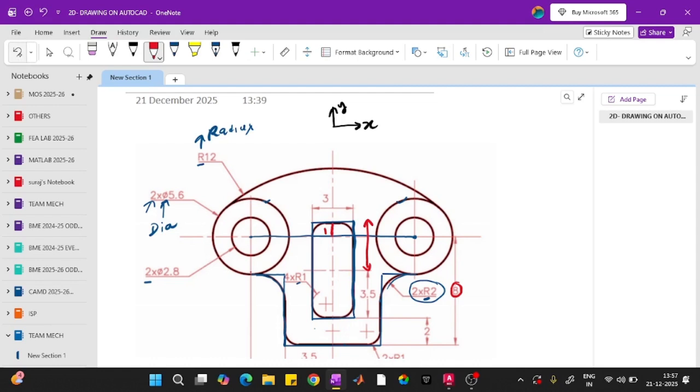And also you can understand it from the arc of this corner. The arc radius of this corner is 1. So this is the arc of radius 1, and the center is here, so this is also 1. So I'm going to make the line in this direction of 1 mm, then in this direction 1.5, and then 7, and then again on the left side it is 3, and then again 7, and then on the right side we will connect with the last point.